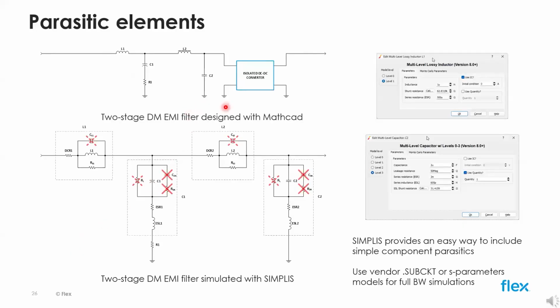The schematic on top is the simple equivalent circuit obtained by mode separation and collapse to single-ended. R1 in this case is a discrete component and not an ESR. The schematic at the bottom of the page is the same circuit but including component parasitics.